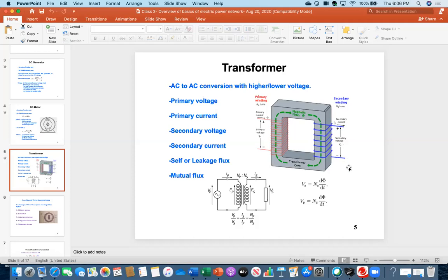That's why the efficiency of a transformer is typically more than 95%, 98, 99%. If you see any power system book or electric machine book, and look at the numerical examples, transformer efficiency is always high. But if you solve any problem of a motor or generator, you will never see the efficiency more than 80% or 85%. Even in real practice it is much less, like 60%, 65%.